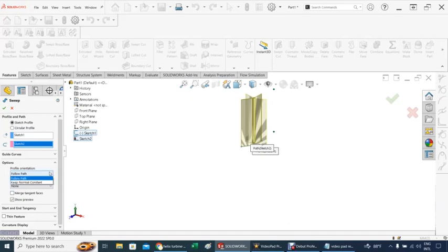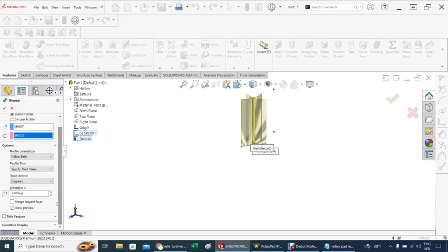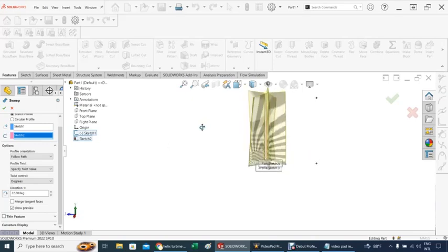Follow path, twist profile. Specify twist value. And here is the funny thing. Let's see how this starts to look as I increase the degrees of twisting. See, it starts to look more like one of those Savonius, or whatever you call it, those types of turbine that are kind of like an impeller from a compressor or something like that. And so let's keep doing it a little.